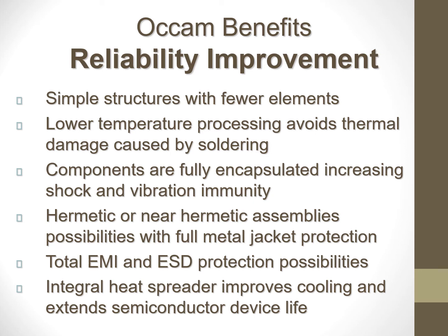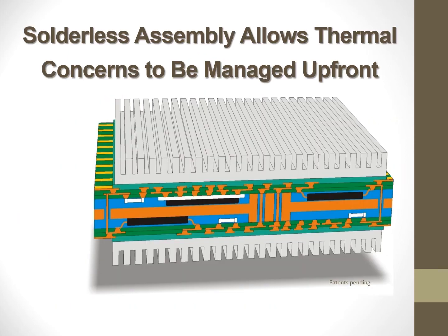And again, that notion of integrating a heat spreader can extend the life of components, as there's an inverse relationship between thermal excursion and the life of transistors in integrated circuits. So here's an example of how a structure might be provided with a post-assembly thermal management structure. The advantage here is being able to address on the front end some of the concerns associated with heat removal; rather than as an afterthought, it can be done on the front end.